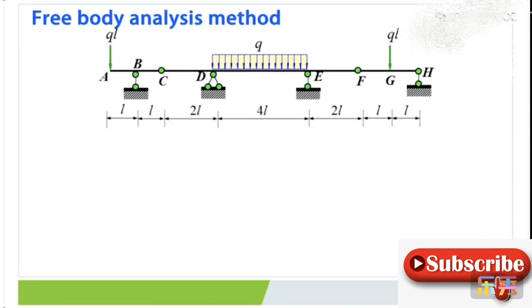According to geometric construction, this beam contains two subsidiary portions, ABC and FJH. The part CDEF is the main portion. So we should calculate the two subsidiary portions firstly, then the main portion CDEF. The free body diagram of each portion could be drawn.